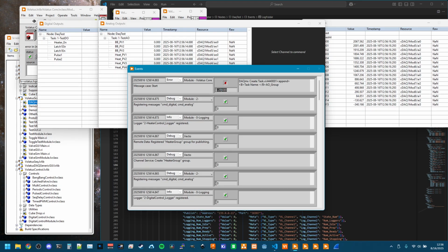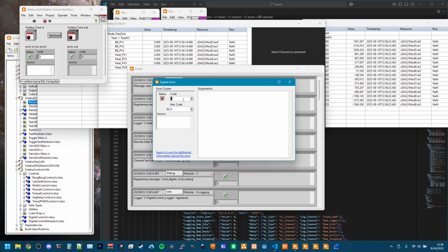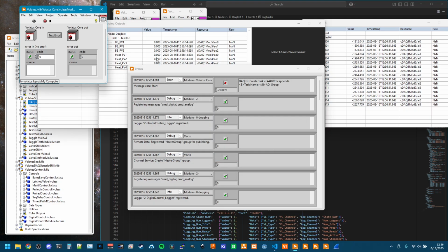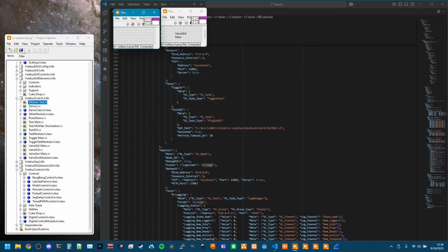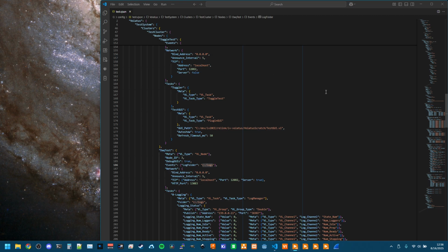Oh, wow, cool, a DAQmx error. What you got for me? Task name specified conflicts with an existing task name. That is because before recording this video, I probably didn't shut something down cleanly. So we're going to fully close down LabVIEW and restart.